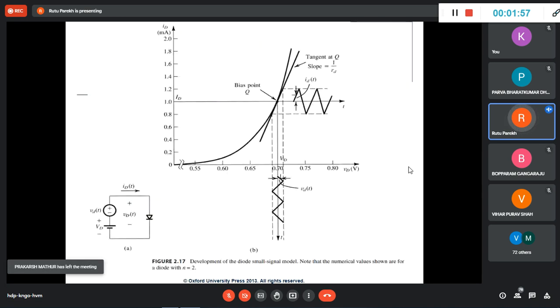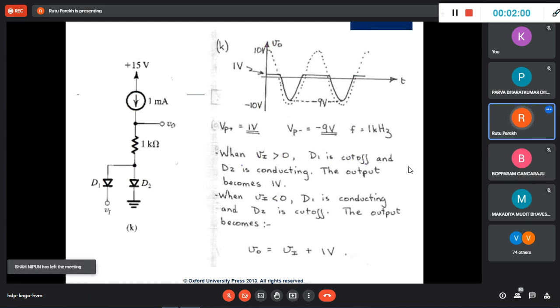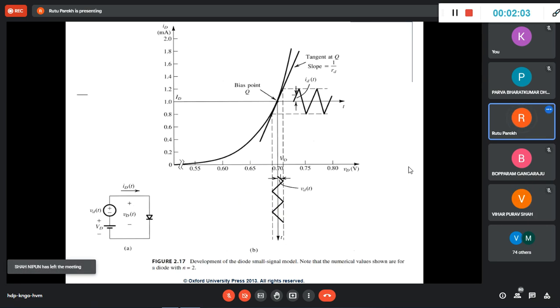I'll start with this point, although I had spoken about it last time. Now we have to build circuits, and it's all about I and V. How much voltage? Because every application has a different voltage and different current flows, or because of the change in the current, there's a change in the voltage and vice versa. The diode has its own IV characteristics, its own nature. You are changing V, and for that specific V, you will have a specific current every time you operate the diode at that voltage, right?